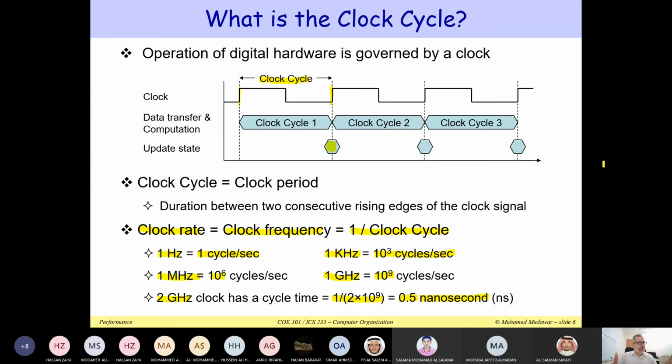this actually means that you have to use a slow clock. That is not related to the power consumption. This is related to the delays that exist inside the gates and inside the circuit. But today the gates are a lot faster than decades ago. So they can be switched on and off very quickly. So you can easily use gigahertz. So the clock frequency has improved by a factor of more than 1000x, maybe 10,000x or 100,000x if you go two decades ago.